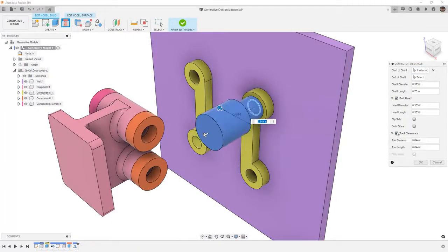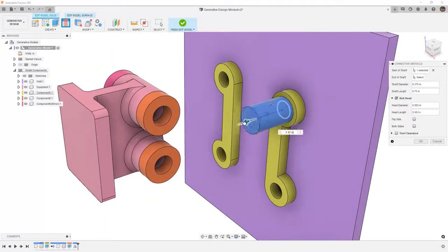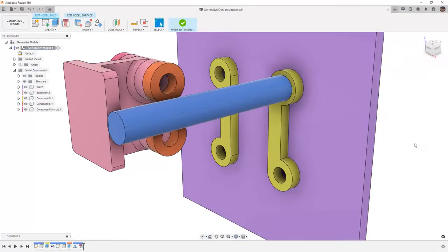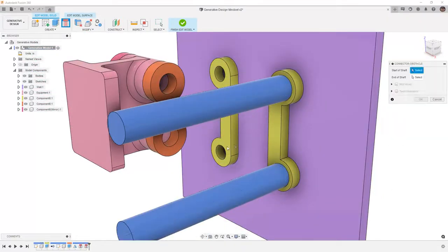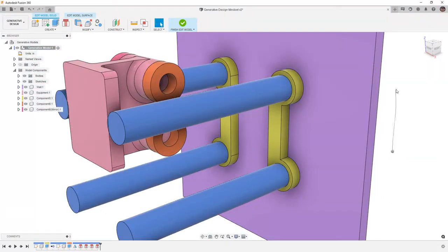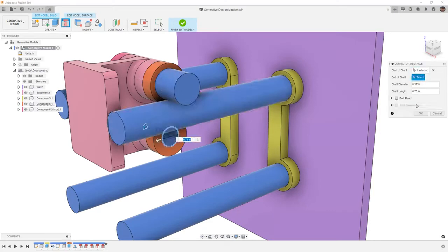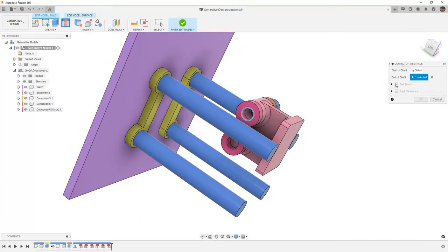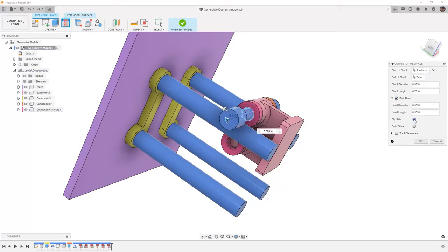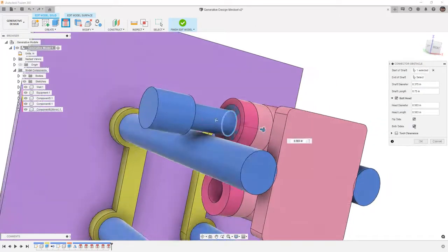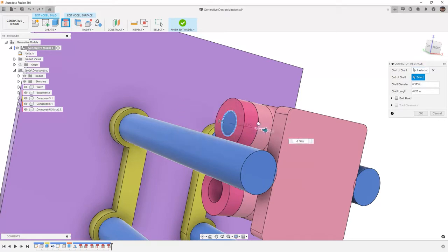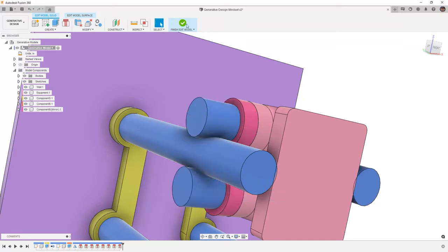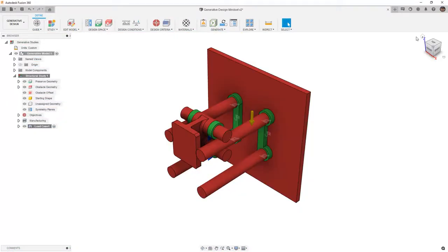While making the shift to generative design, we need to think less about design and more about constraints. One of the key concepts to making the most of generative design is understanding the negative regions of your design. Things like bolt head clearances, tool access, and movements of mechanical parts. We take these into account on traditional designs, but only because we're working one feature at a time. With generative design, we need to build all that information in from the start.